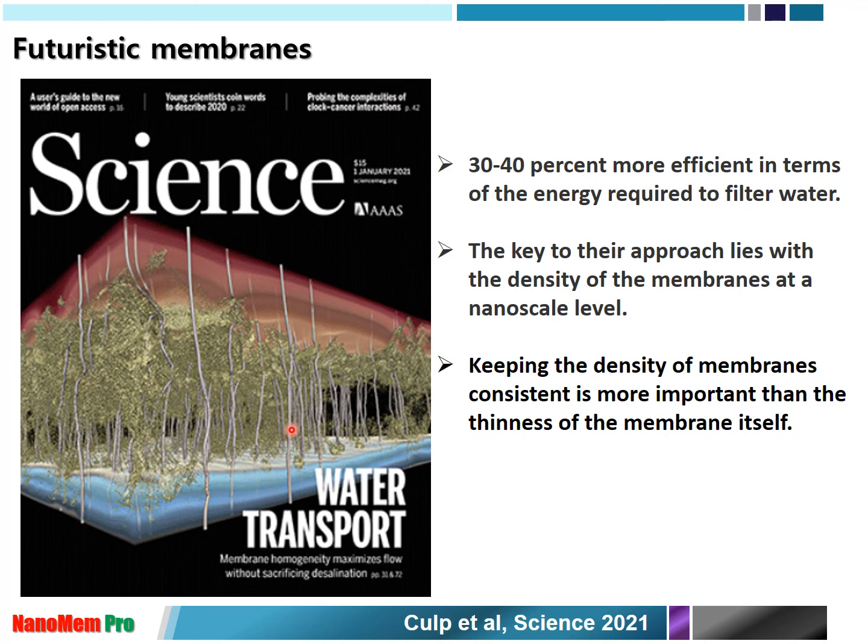A series of polyamide desalination membranes, which were synthesized in an industrial scale manufacturing line and then varied in processing conditions but retained similar chemical composition, show increasing water permeability and active layer thickness with constant sodium chloride selectivity. Transmission electron microscope measurements, which are on the cover figures in this issue, enable them to determine the nanoscale three-dimensional polyamide density maps and then predict water permeability with zero adjustable parameters.